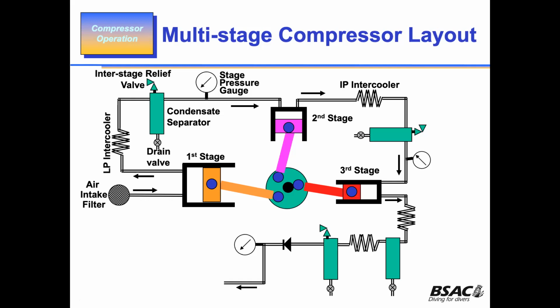It goes into the third stage, and in the third stage, it is pressurized up to your final pressure. Now, when it gets to the end of the third stage, you've got, as it says there, an HP intercooler, and then you've got an aftercooler. Again, this is all necessary to make sure that the air comes out at the right condition for you to put into your cylinder.